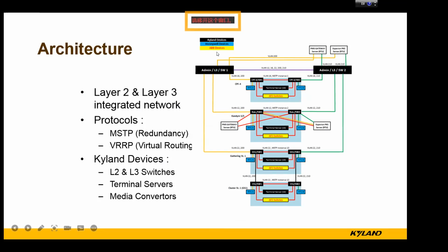But in this network, we cannot use the most commonly used RSTP, since the network is very big and they are connected with each other. RSTP only allows at most 50 nodes in a single region. So in this network, we can only use MSTP to cooperate with the ABB switch.